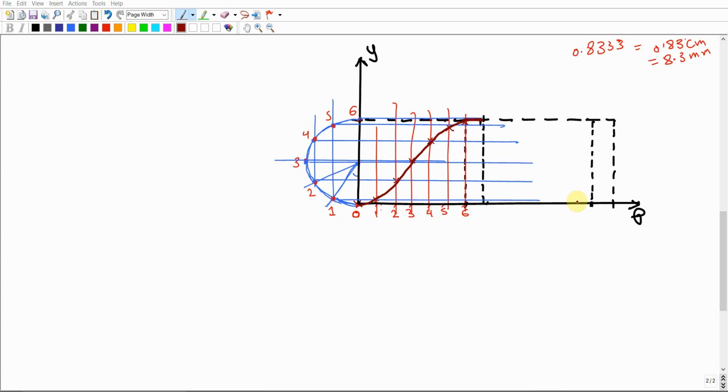So if you divide 150 by 30 degrees, this gives us 5, which indicates 5 angles of 30 degrees. Each one will be 1 centimeter. It means that this should be 5 centimeters. Then you're going to break the 5 centimeters down into 6 digits as we did for this one. It means that every digit will be 8.3 millimeters.